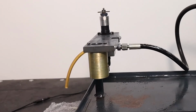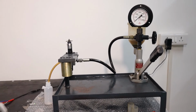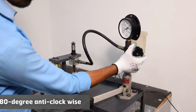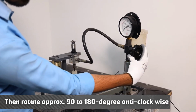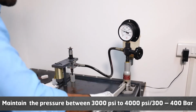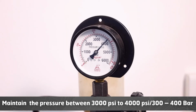Fit the transparent tube at the return line to measure the back leak. First tighten the pressure relief valve by rotating clockwise direction and then rotate approximately 90 to 180 degrees anti-clockwise. Build the pressure using hand lever and maintain the pressure between 3000 psi to 4000 psi. That's 300 to 400 bar.